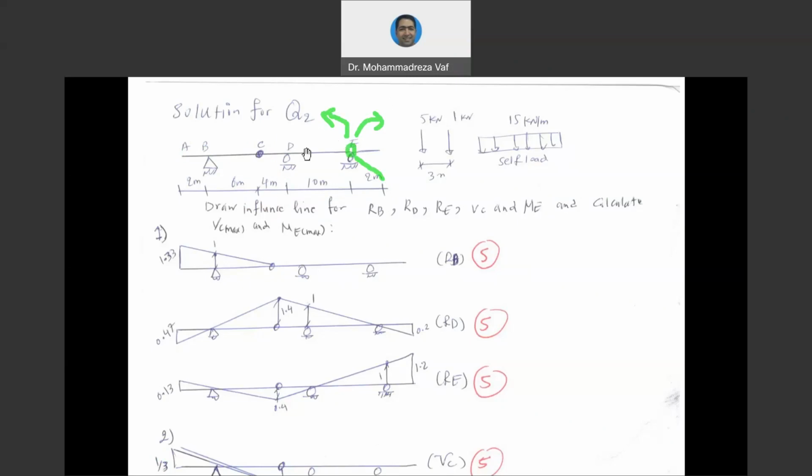However, on the left side, you need to see whether it can rotate or not. You can see there is a support at point D and there is a support at point E. And these two support reactions are not going to allow rod ED to move. And if rod ED doesn't move, the other part of the beam also cannot move. Therefore, we are going to have a deformed shape similar to this one.